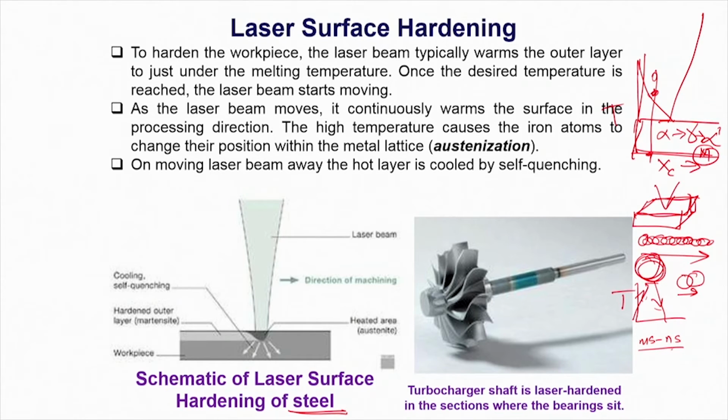Because of which this kind of a sequence happens. Ferrite transforms to austenite, and austenite on fast quenching undergoes martensitic transformation. We must have adequate carbon, otherwise we don't get sufficient hardening effect onto the portion we have actually irradiated.